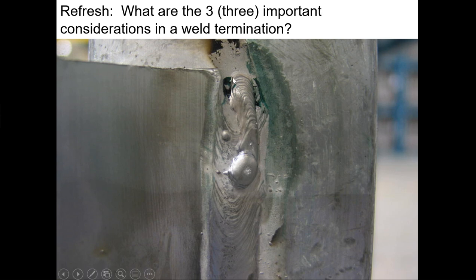So a TIG welder was used, of course, got it hot and brought it back and started, of course, welding from the end and bringing it back up on top. Finish from the ends. Start here if there's an end condition problem and weld towards this piece, right? There's no porosity, there's no cracks, but we don't have fill.